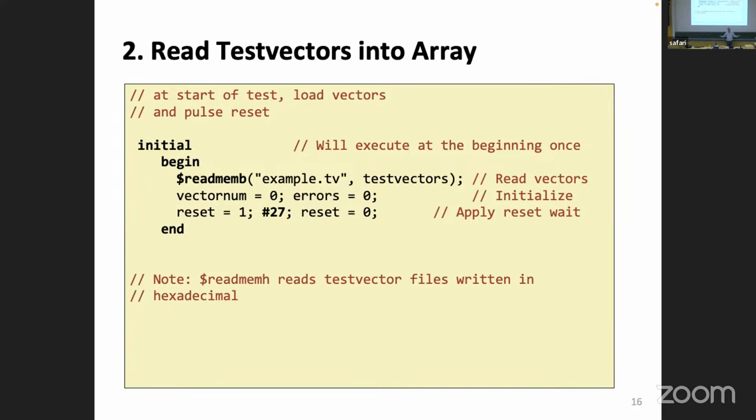Notice that Verilog doesn't care. If your lines contain 50 characters, it would have taken the first 4. If your file contains only 2 characters per line, well, the first 2 of those test vectors would be assigned. The rest would be unknown, X's. My test vectors were not initialized, so they were all filled with X's. The moment I read this file, a certain number of them will be overwritten with the contents of the file, and the rest of them will stay in the memory as X's.